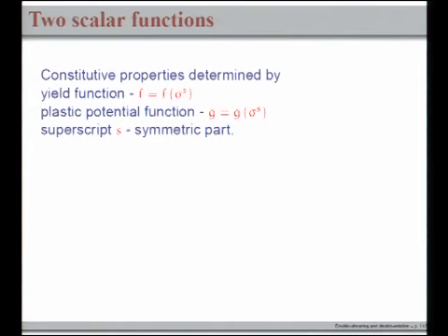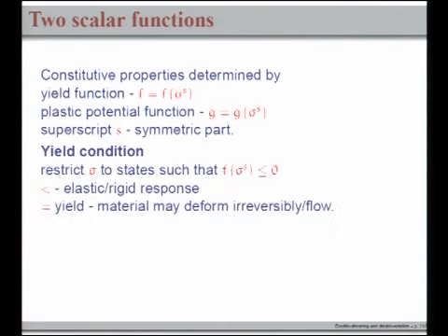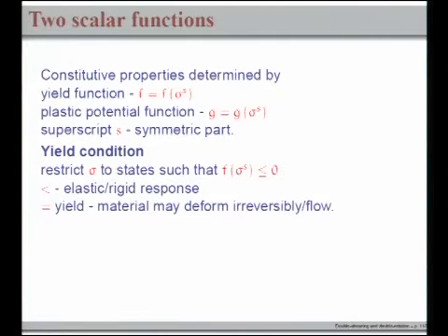If we want to definitely include the anti-symmetric part of the motion, then we would have to decide what to do about that. And we could either include the anti-symmetric part in F, or we could have a second yield condition, but I won't do that today. So a yield condition, of course, merely restricts the states of stress that the material can feel, if you like.